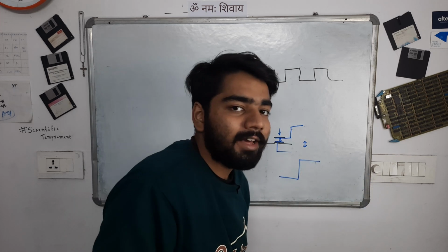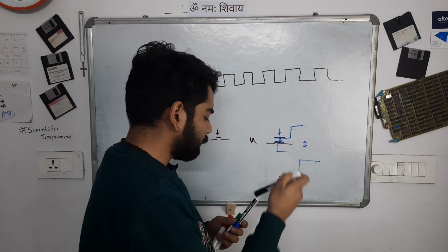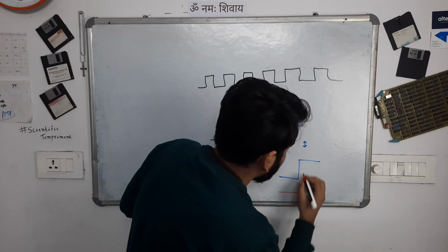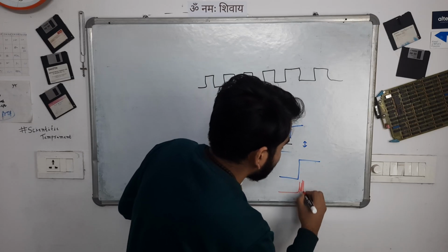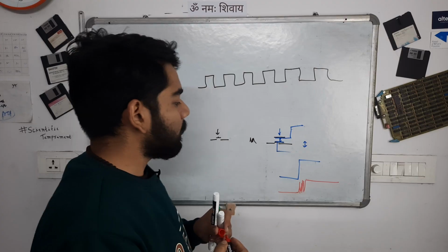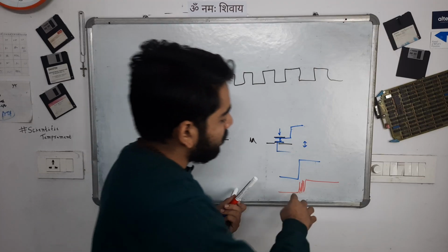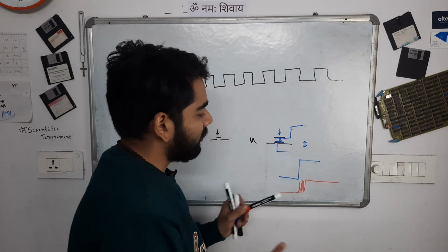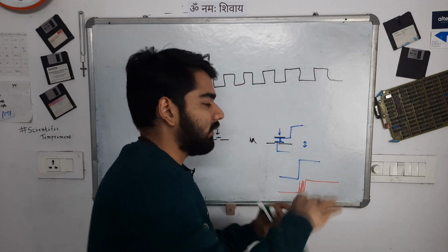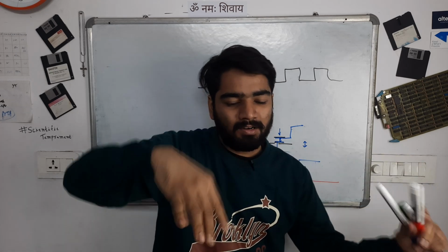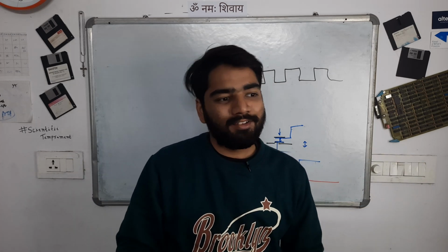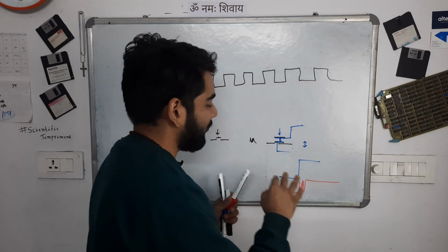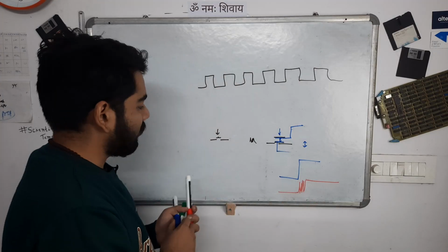This sort of clean thing should happen, but because of the bouncing of the button, when you come near this edge, these transitions happen, and then you go to high state. Why do these transitions happen? Because physical connections are not ideal in the real world. Basically the button loses contact, bouncing between the contacts, which we will explore again in the next few videos. This push button is one of the reasons.